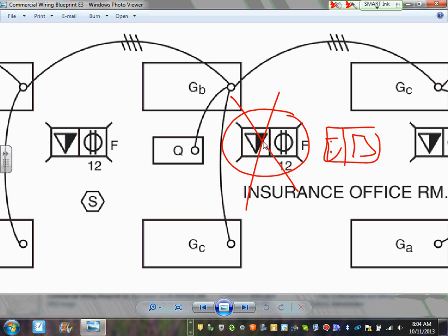So when you have an open office like this, because you have to wire data and phone here, there are two options: either you come up with a power pole right here, or you come from underground with typically one junction box split into two, one for the low voltage, one for the high voltage, and you have a flexible non-metallic or flexible metallic liquid-tight conduit tied to the furniture. That will take the data and the phone separately into different channels inside the furniture, and that's how a cubicle is wired. They buy wired furniture with devices, and they tie in at the end with a junction box to that furniture.